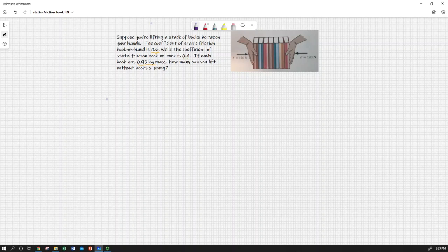But think in terms of, I can draw a free body diagram with any number of books in hands, one book, all the books, because everything is in static equilibrium. So it doesn't matter if I draw an FBD of 6 books together, I can pretend they're welded together because I'm going to establish a condition of equilibrium that says nothing's accelerating. If all 6 books aren't accelerating towards the floor, 1 out of 6 is not accelerating. I will impose that and then see what conditions are needed to keep all 6 from going down together. And then I can make sure that is bounding to what would be needed to keep any one book.